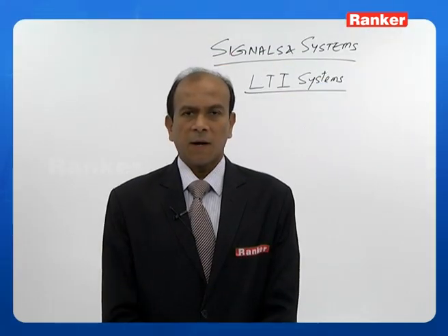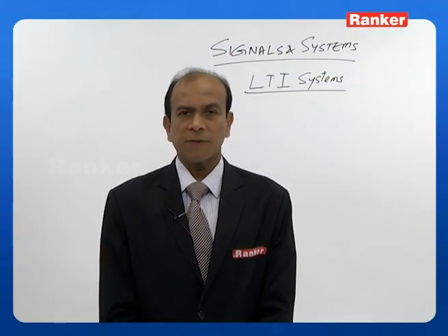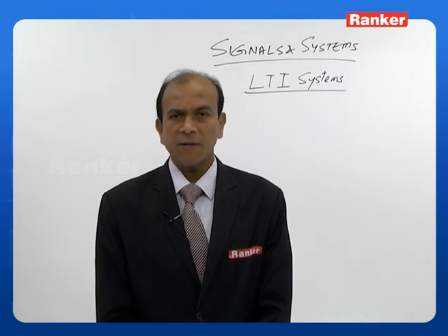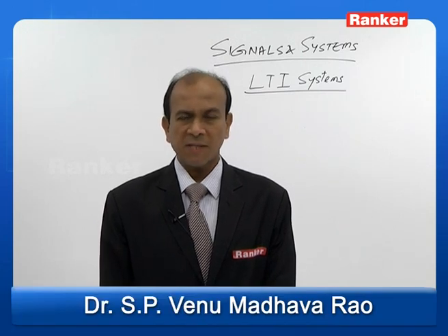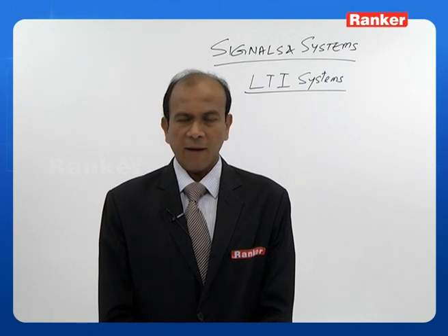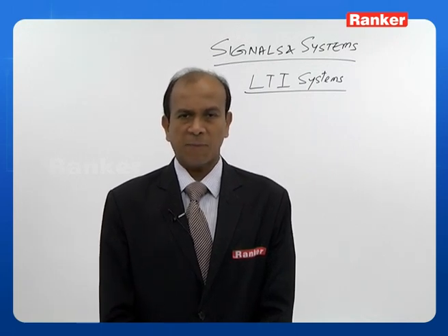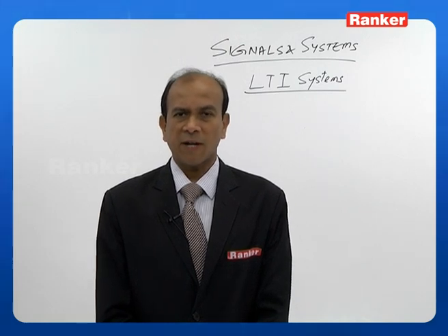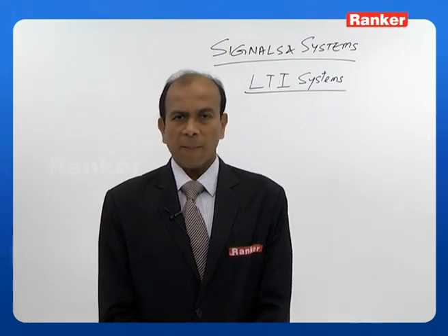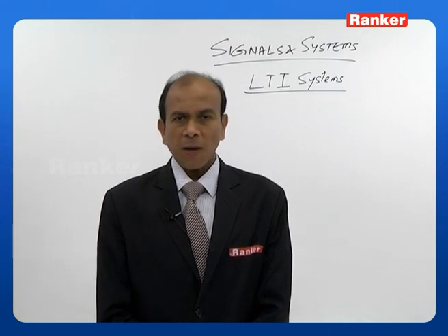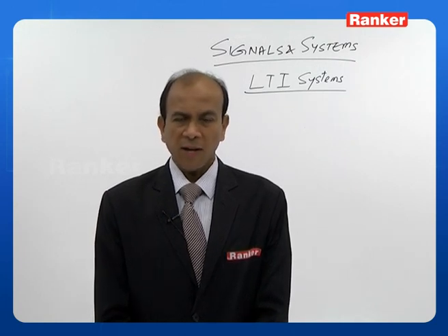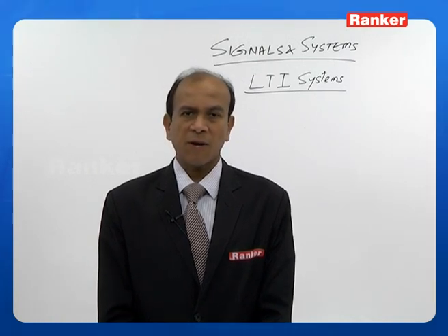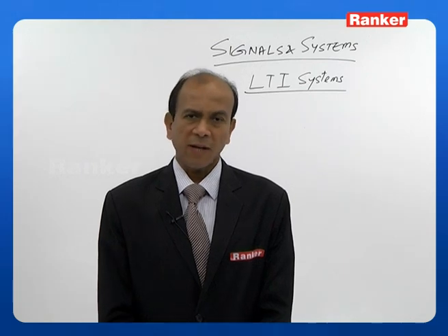Now, let us see the importance of impulse response for an LTI system, that is, a linear time invariant system. The output of a system for a given input which is an impulse function is very important, because when I calculate the transfer function, either the Laplace transfer function or the Fourier transfer function of a delta function, the output is invariably 1. That means, when I feed an input x of t equal to delta of t, then h of t will be y of t, because the Laplace transform of delta of t is 1 and the Fourier transform of delta of t is 1.